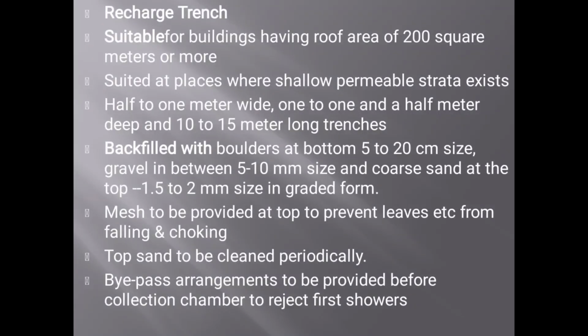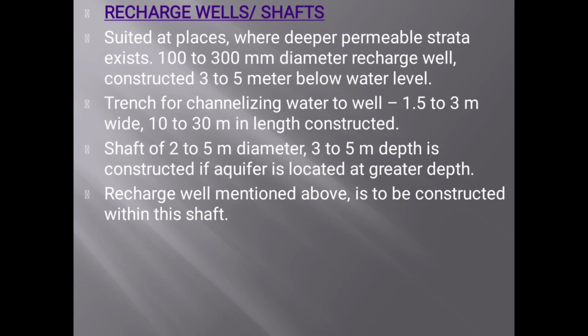Next one, recharge trenches for buildings of 200 square meters and more. Permeable strata exist; trenches half to 1 meter wide, 1 to 1.5 meter deep, 10 to 15 meters long. This is what we see like in rainwater harvesting in rural areas. This is also what we see in rainwater harvesting in rural areas as recharge shaft.